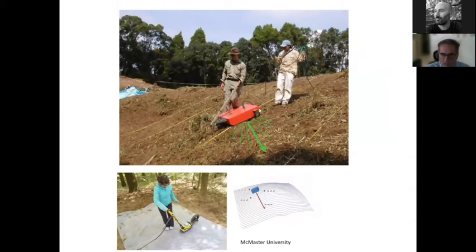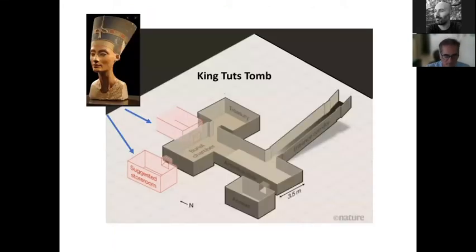And when you're working particularly on sites with changes in elevation and the antenna is connected to the surface, you have strong tilt in three directions, or the yaw, pitch, and roll. There was actually a university, McMaster University, back in about 2010, 2011, that put a tilt sensor on their antenna, and then we used the GPR Slice software to put all that data into its vector space. Let's go to a site.